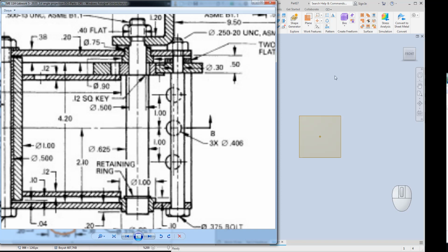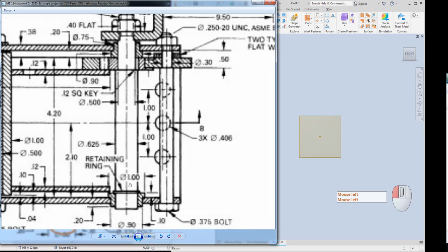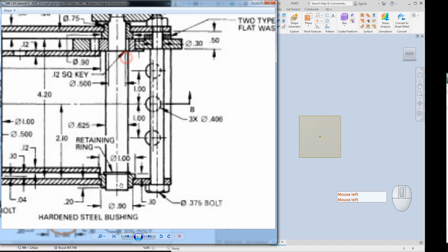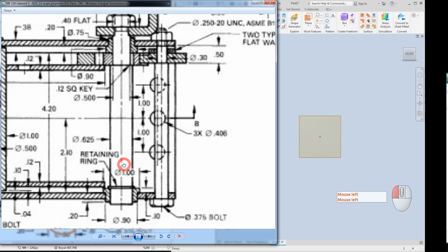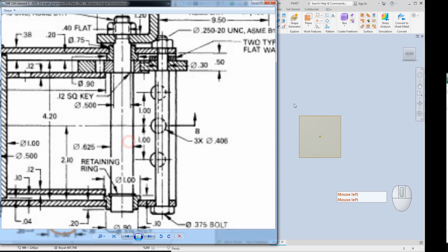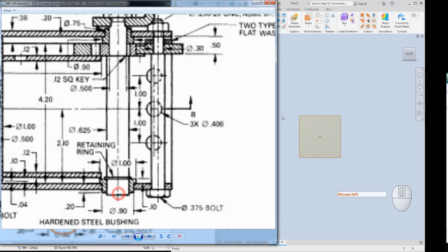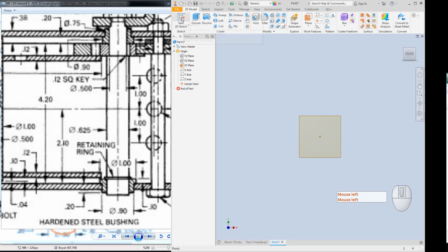I will use the revolve technique because we have some features, and also we have to revise some parts of our model with this technique. The other technique, the extrusion on and on technique, will not be much better for this reason. I will just choose this point here and use it as my origin point. I start a new sketch after this on the XY plane.